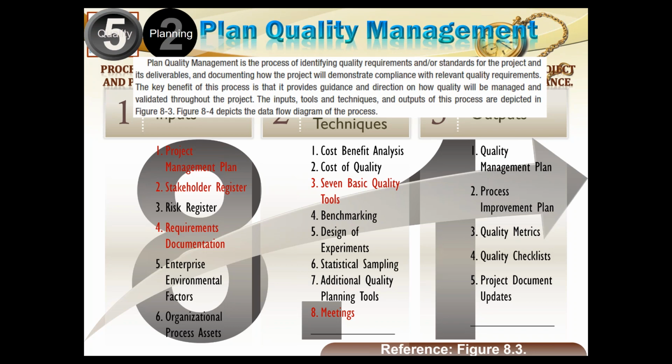Then if the sample size is too big, you cannot do the destructive testing of all the samples. If you are manufacturing biscuits, you can't open all the boxes of biscuits to check how they taste. You just have to sample. So the statistical sample would be a random sample of some certain predefined percentage. Only that many boxes will be opened, and that would stand for all the boxes which have not been opened. So you will do a select sample testing, and this is called statistical sampling.